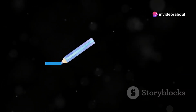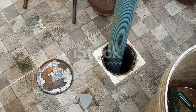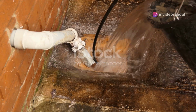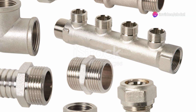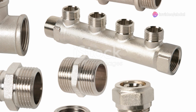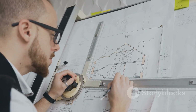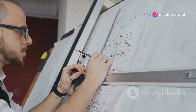Similar to water supply lines, select the line tool and choose a layer for your drainage lines, like drainage. Start drawing lines from each fixture, connecting them to larger drain lines that eventually lead to the main sewer line. Remember to include fittings like elbows, T's and Y's to connect pipes at different angles and branches. You can find these fittings in your plumbing library or draw them yourself. Always double check that your drainage lines have the correct slope to ensure proper flow.